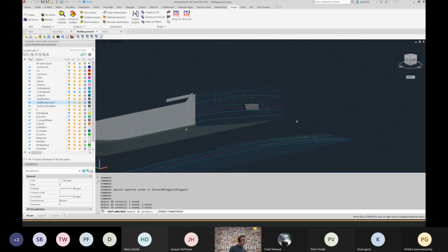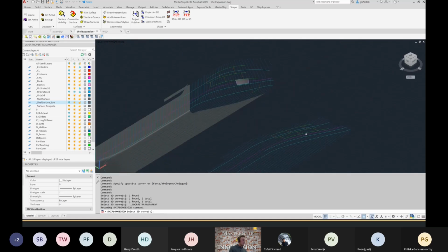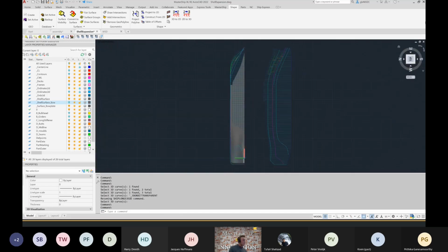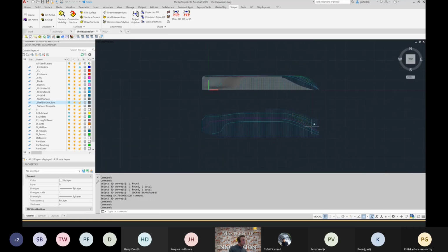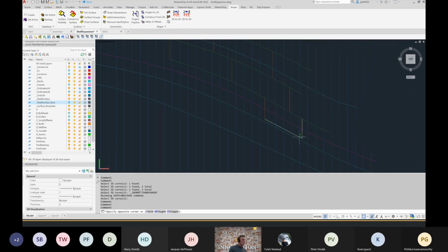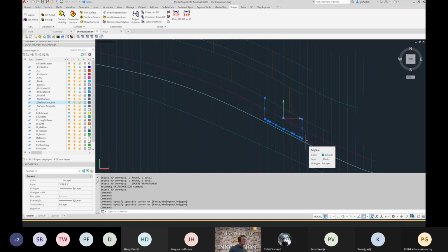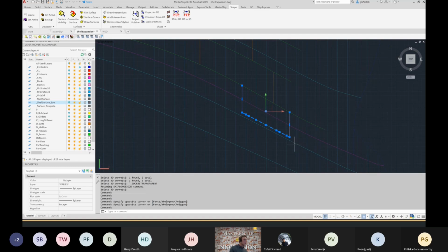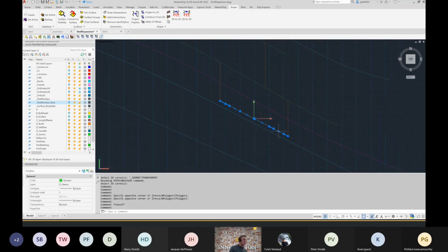Then I press enter, and at the moment I press enter, you will see it appearing here on the shell expansion. So it's now here. I'll show it in the top view. So these are the butts and seam lines that we just projected. I have to say this looks fine to me, but we can also have the case that, for example, this seam line was too close to this deck.